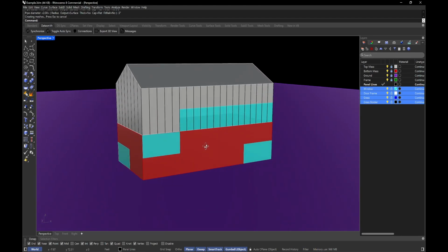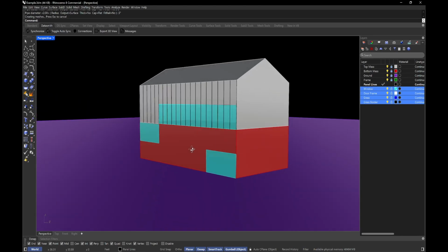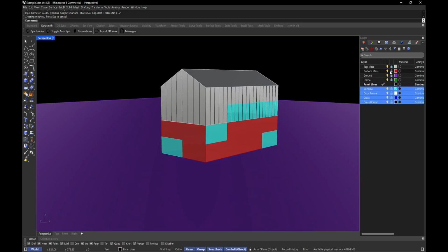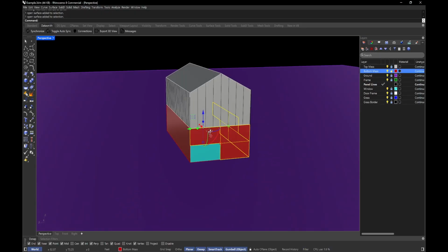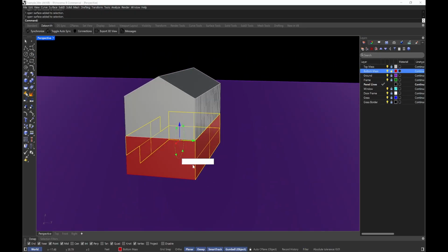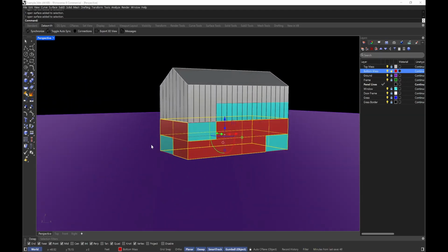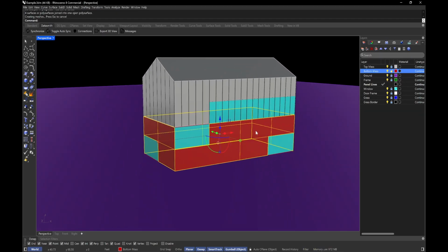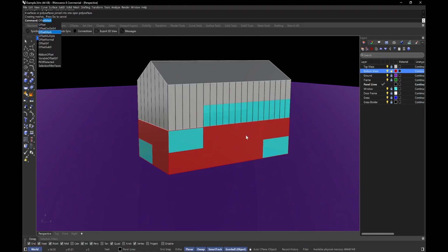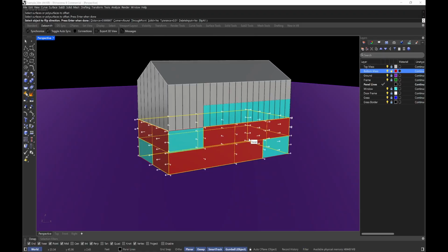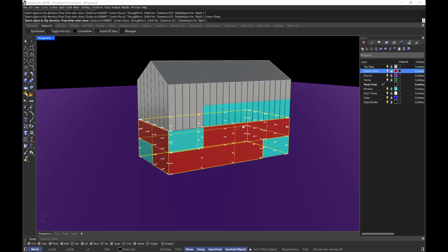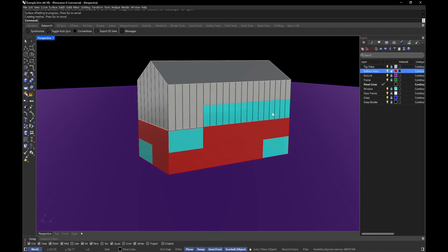And then before I do it to the windows, let me just go ahead and join. That's why let me unlock the bottom mask. Let me go ahead and join this mask now, like that. Let me join it. And I'm gonna do offset surface, right? And I'm gonna F for flip the direction inward. And corner, I'm gonna do sharp, solid yes. And distance, we'll give like 2 feet. Like that. Okay.